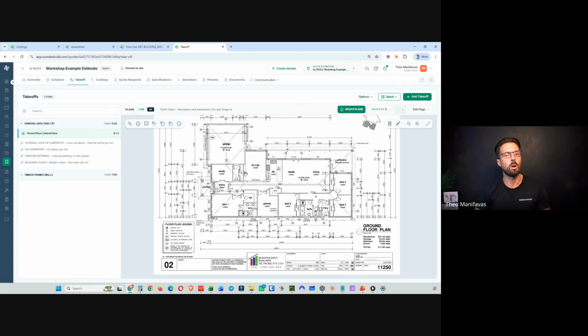I'm not sure if you are, Rob, but I was having a chat with him about this, and this is what got me thinking that even though you can create efficiencies, say that plaster, for example, where if I just linked it back to the ground floor area for the ceiling plaster, I'd get my plaster square meters for the ceiling, but then I'm not factoring in the wet area board, and then I would have to go in, or the estimator would have to remember to go in and do a deduction for wet area board and apply that wet area board square meters.